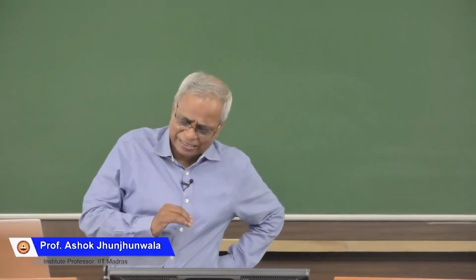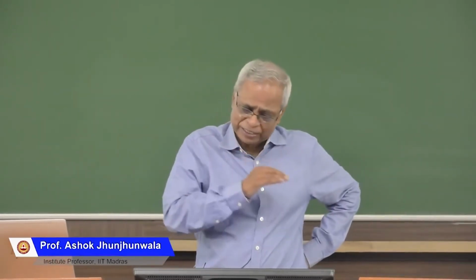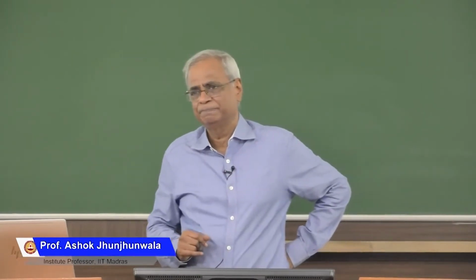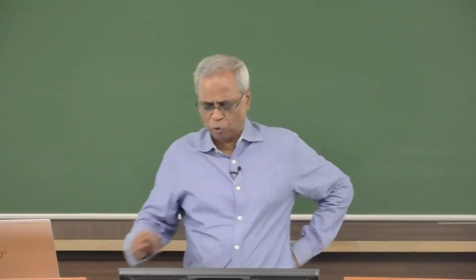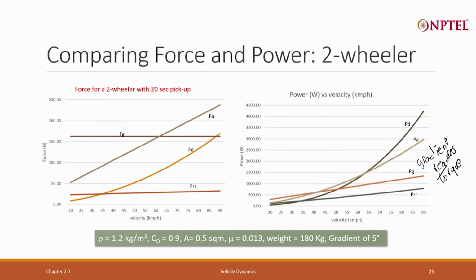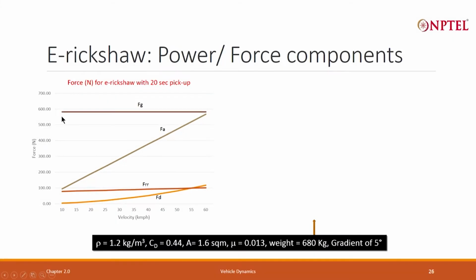difference. I am taking the same gradient of 5 degrees, and for sake of calculation I am saying the same pickup, 20 seconds for a specific speed. Look at the force. If you see, the gradient force is now very large. Compare it with the gradient force that was required here, you can see it on this screen, it is more like 160 Newton. Gradient force required in this is 600 newtons.